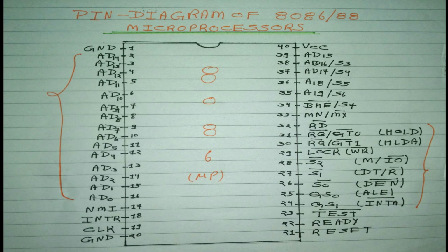And the pins A8 to A15, the 8086 address data bus lines, compose the multiplexed address data bus of the 8086. These lines contain address bits A8 to A15 whenever ALE, address latch enable, is logic 1. Otherwise the data bus connects to them. These pins enter high impedance state whenever hold acknowledge occurs.